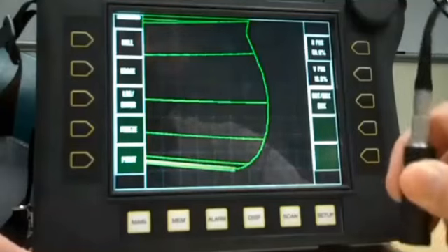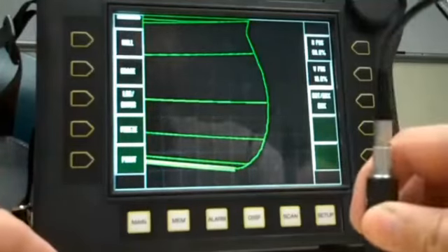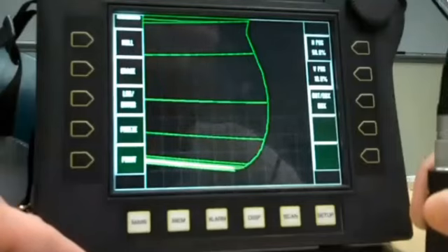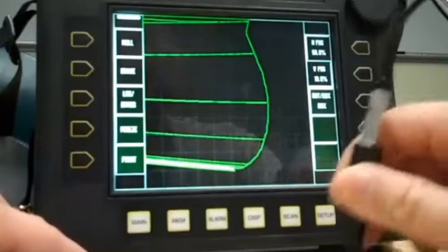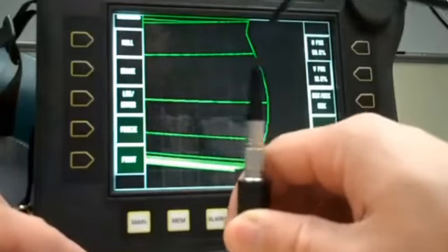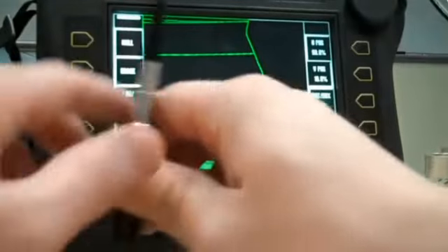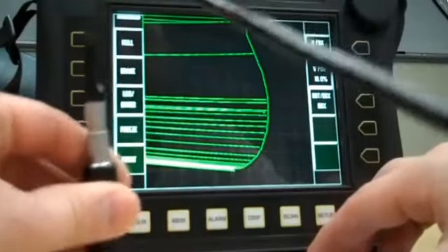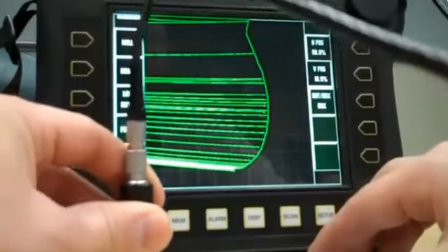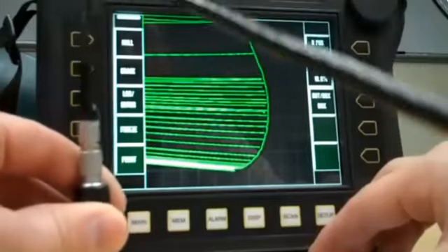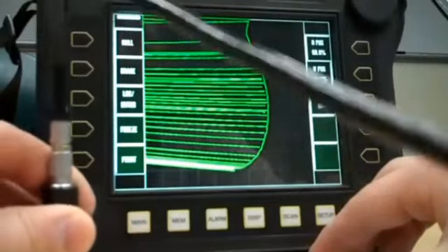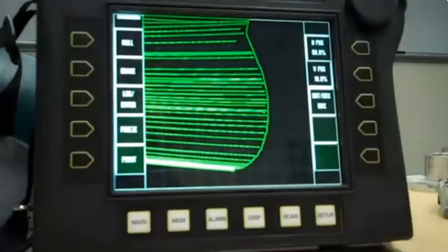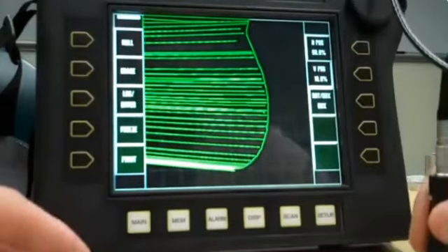Any one of those impedance points, as you can see as I get closer to the edge down here, I've just about maxed out that probe, so there's really not a big difference. If I would go to a lower frequency, you'd see those lines separate a lot more. And you see these lines just fill in here. Whoops, let's go back a little bit. These are all just thickness points now. As I walk across the screen, you can see the closer I get to the thin, the quicker those lines move. All I'm doing is looking at the end of that conductivity curve. That's just the thickness.